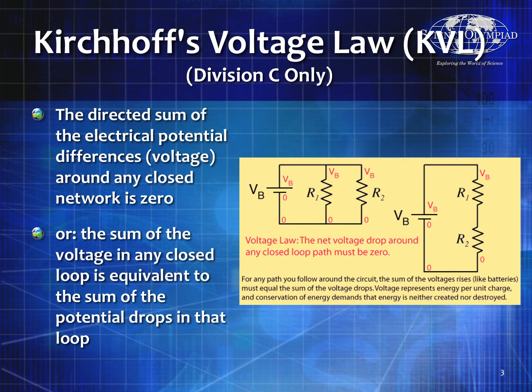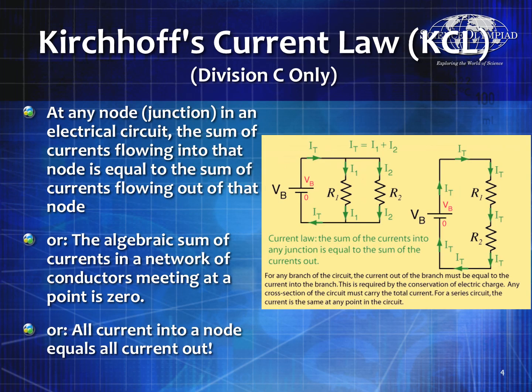We also talked about Kirchhoff's Voltage Law, which, while it is only a Division C concept, is very useful in circuit analysis. So if you're able to understand it in Division B, I would recommend still using it. Basically it's doing a loop around anywhere in a circuit, and all the voltages end up adding up to zero. That's how we're able to know that the voltages are the same in a parallel circuit, and how we know the voltages are split in a series circuit.